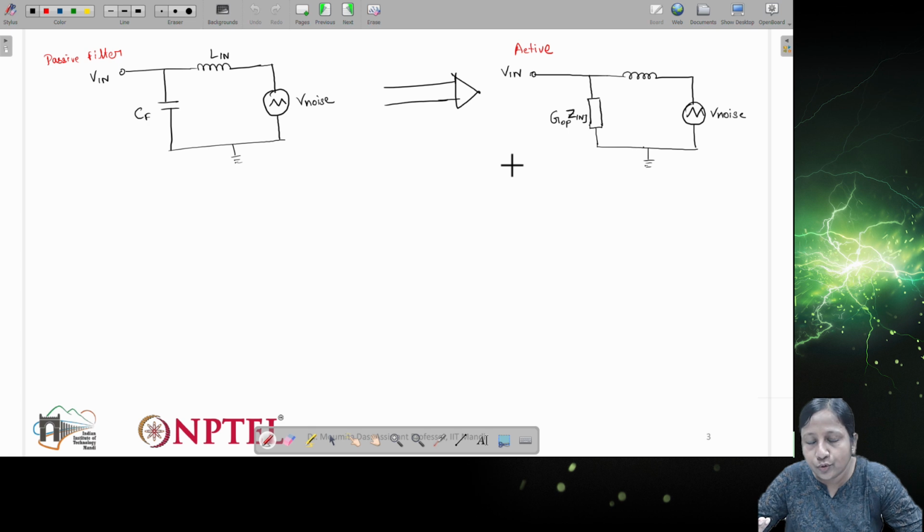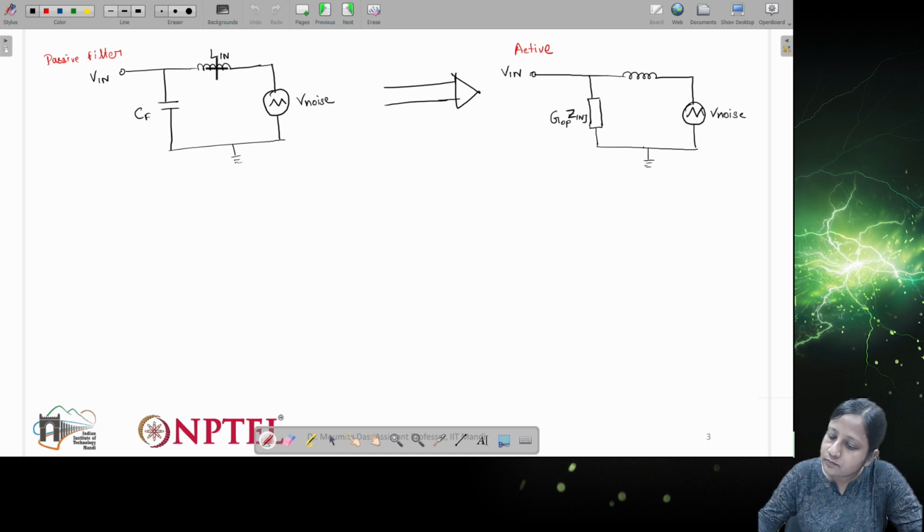Like we are trying to reduce the system size. Again, by reducing the system size, we are increasing the EMI noises. And in order to suppress this noise, if we increase the filter sizes, then the advantage of going for high frequency will probably not be there, right? But in this case if we use an active filter, then this active filter can provide different levels of noise cancelling signal as per the requirement. So that is where the advantage of the active filter comes, right?